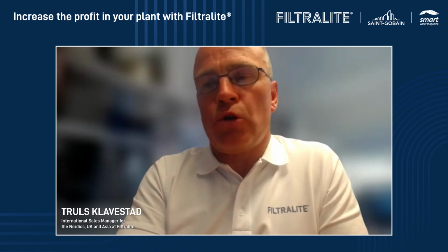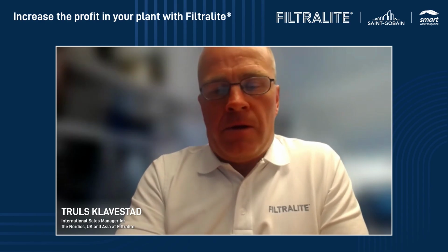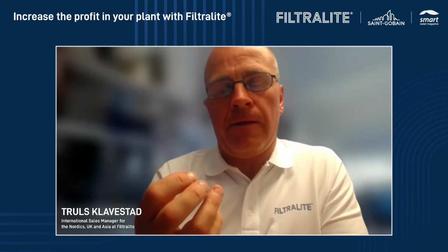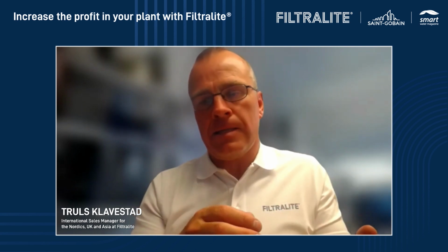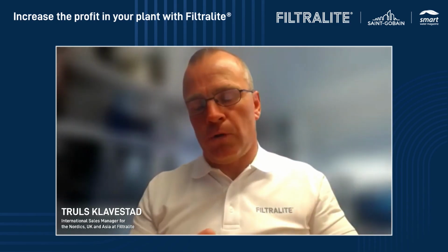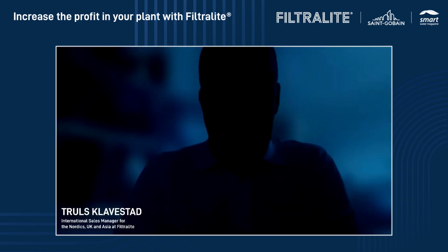I was running this pilot for, I think, 5-6 years, and I also saw that because activated carbon is a much softer material than Filtralite, the grain size went down a little bit, like anthracite. So the performance for turbidity removal also went down, because the grain size slowly went down.